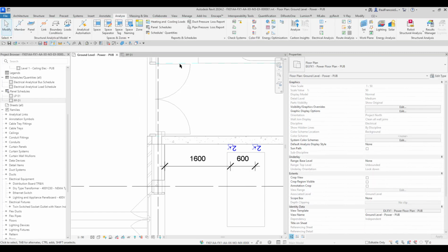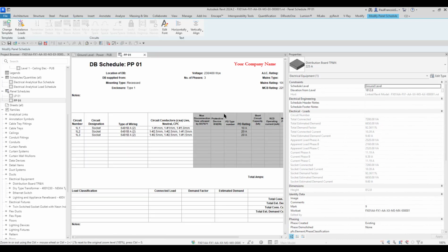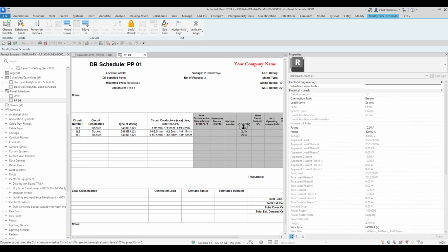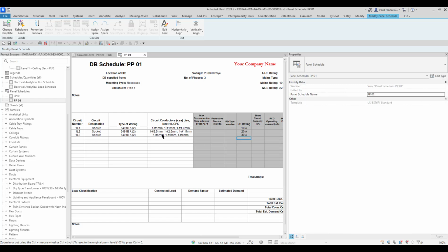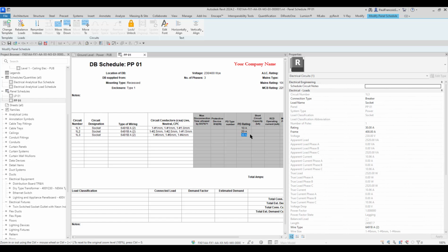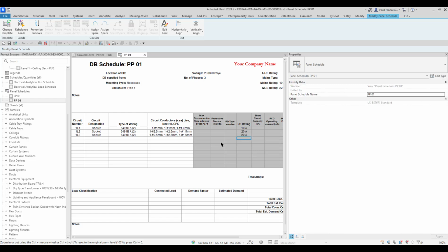A way that you might want to do that at the end of the project, remember you might just be in charge of the project, you don't know what the others have done. So with this 10 amperes for instance, as you change the amperage, let's do this to 30 amp. Have a look at the wire sizes. The wire sizes will update. So there's 20, there's 30. The wire sizes increase to 6 millimeter. There's a 20. So your breaker sizes also have an influence on your wire sizes.